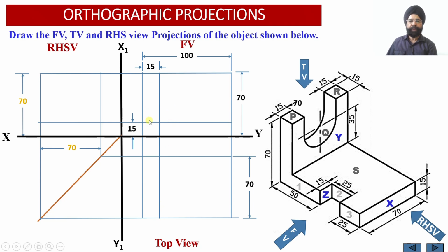Now this is the web vertical one, and this is the horizontal component of the web over here. Next, we observe that in the horizontal web, from the right hand corner as we move along 25 millimeter towards the left side, there is a rectangular slot provided over here. The dimensions of the rectangular slot are: width is equal to 25 millimeter and the depth of this rectangular slot happens to be 15 millimeter.